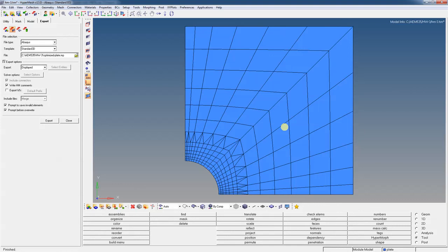In industry, sometimes they take a little bit different approach. In the automotive industry, for example, if they're looking at sheet metal, they may have a standard size element for sheet metal, and they may use 5mm elements. And that's maybe coarse in some areas, but they have enough experience knowing that if they get a stress result, they should maybe multiply it by 10% to get the answer for the stresses near that spot.